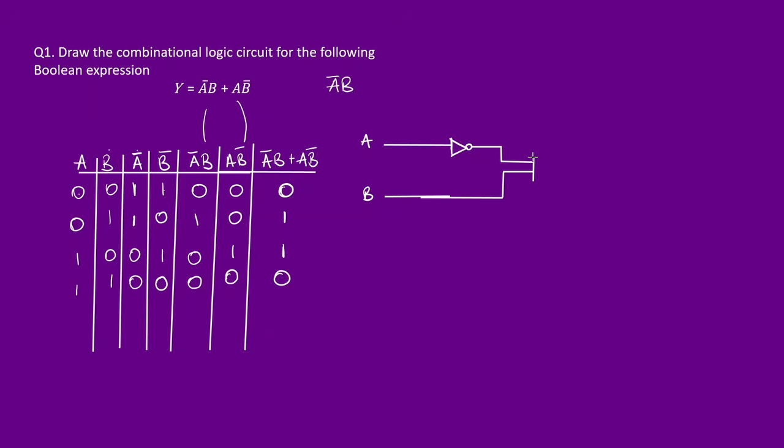So the outputs of this, recall, you have A over here, you have B on this line. This gets negated. This comes not A. This is still B. And you have not A and B entering your AND gate. And so your output becomes not AB. Cute stuff. The second half is A not B.